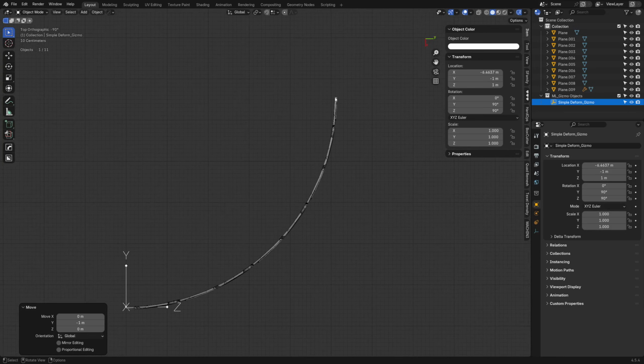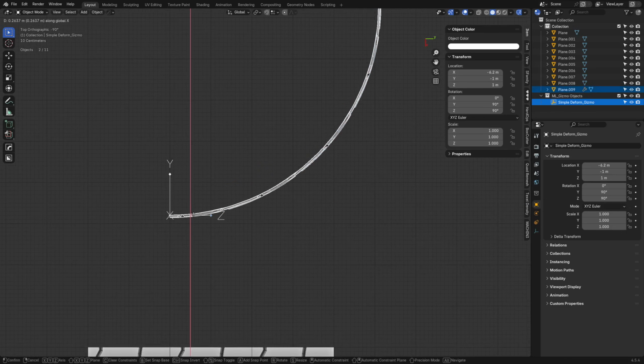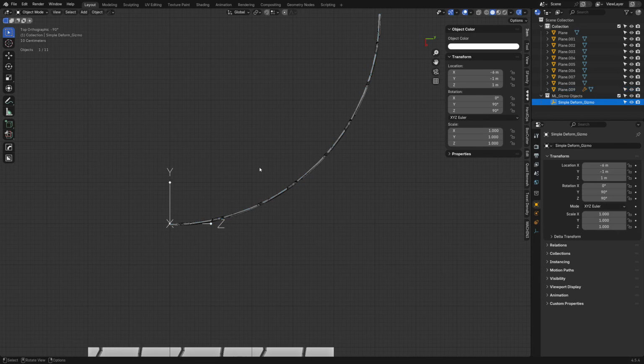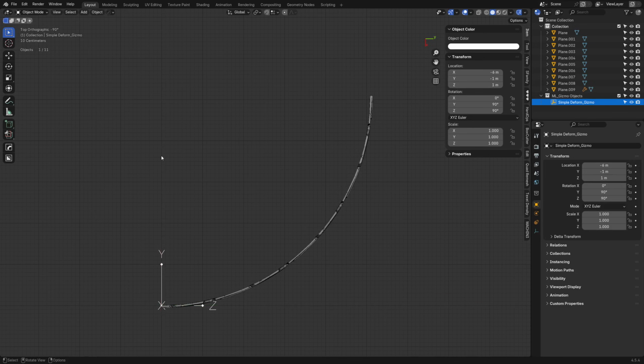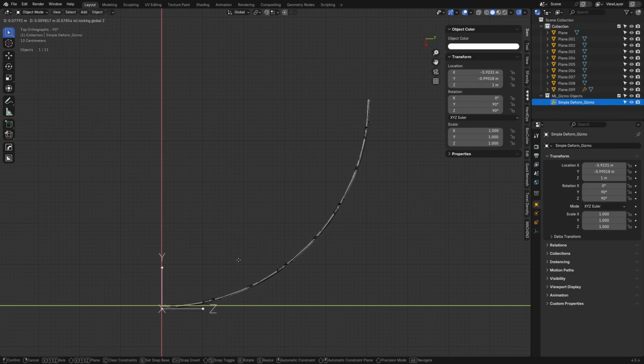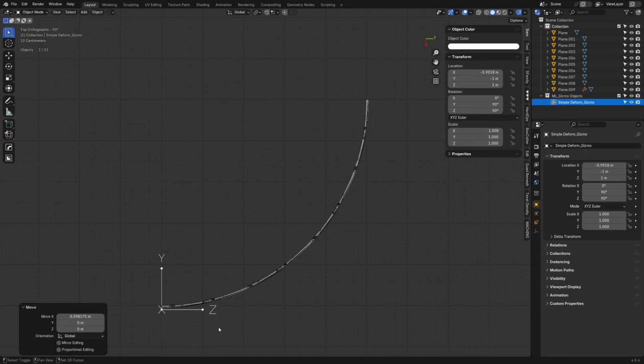So the idea is we want to get it back to another grid point, like a modular piece, right? So we'd influence this a little bit. Press G, Shift Z, use the move tool, whatever you want. But we're just going to try to modify it a tiny bit. Might just be on Y or X or something else that you have to move until you get it back exactly where it needs to go.